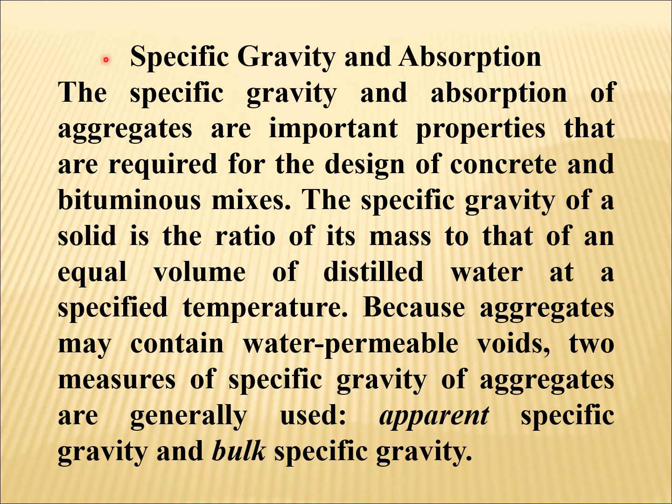Okay, now the specific gravity and absorption. Here the absorption means the water absorption. The specific gravity and absorption of aggregates are important properties that are required for the design of concrete and the bituminous mixes. The specific gravity of a solid is the ratio of its mass to that of an equal volume of distilled water at a specified temperature.